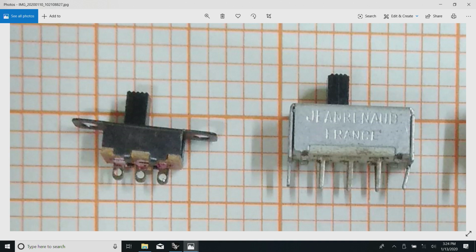Typically, if it is the very simplest thing like the usual PVC wires, in short connections and all that, even today it is preferred to have single core PVC insulated. So, you pass the core through that small slot. We have a small slot here. So, the wire is passed through that and you just solder it. While soldering is another technique, you can pick it up in the other design things. In this case, the termination option is very, very important.